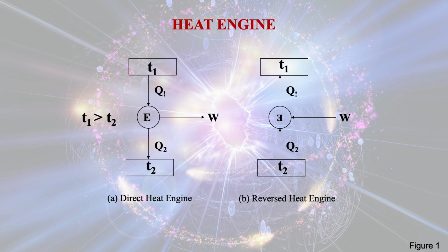But in the reverse heat engine, if you want to transfer heat from a low temperature region to a high temperature region, we must do work. W is the work done on the reverse heat engine to extract heat Q2 from a low temperature region and transfer it, as heat Q1, to the high temperature region whose temperature is T1.